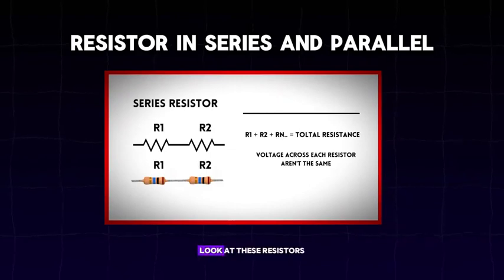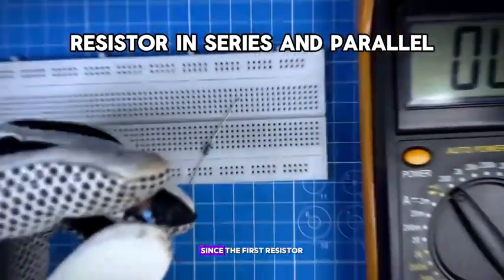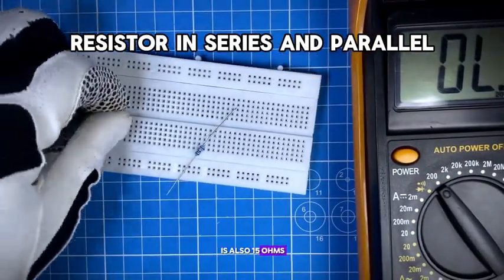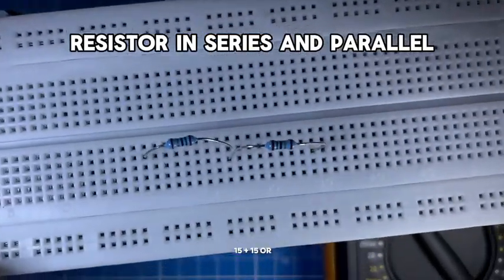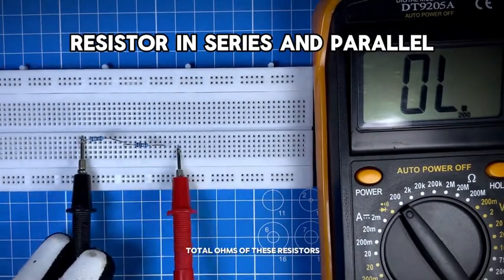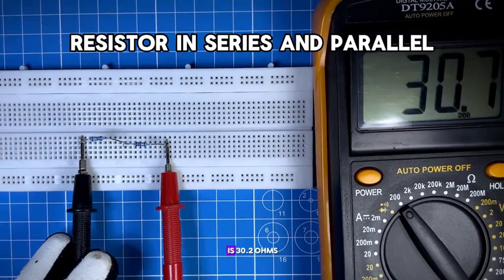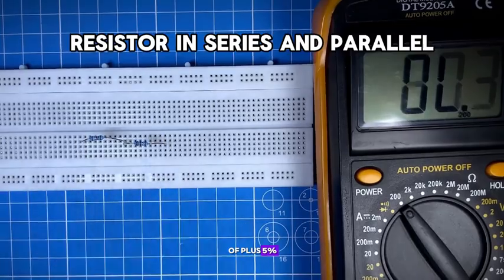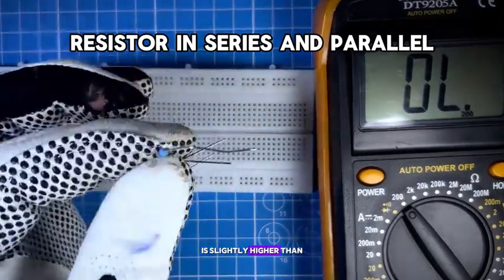So practically, look at these resistors. The two resistors are connected in series. Since the first resistor is 15 ohms and the second resistor is also 15 ohms, the total resistance equals 15 plus 15, or 30 ohms. As you can see in the multimeter display, the total resistance of these resistors in this series connection is 30.2 ohms. This indicates a tolerance of plus 5%, as the resistance is slightly higher than the actual